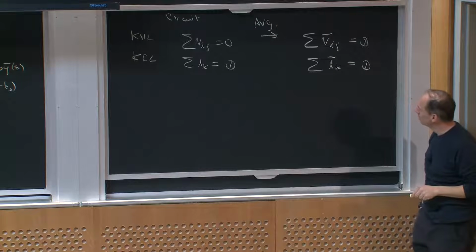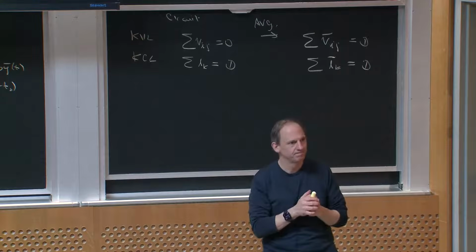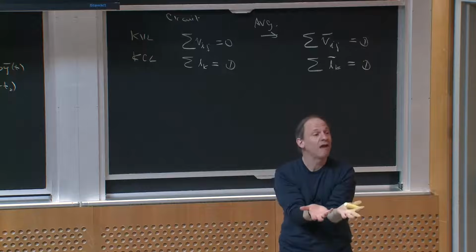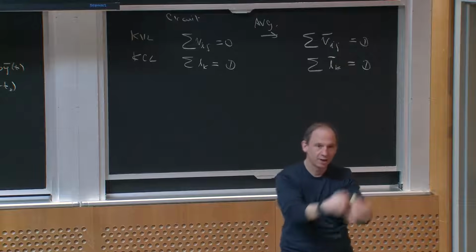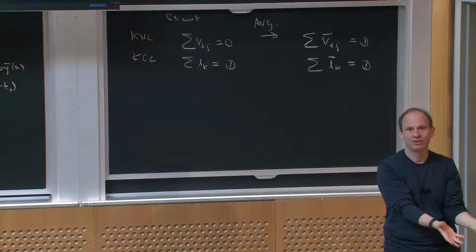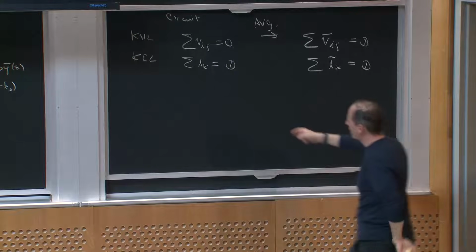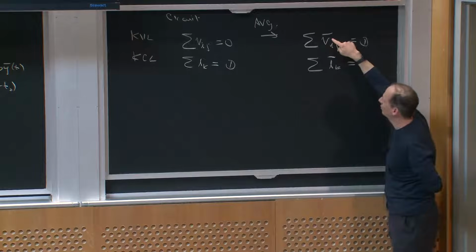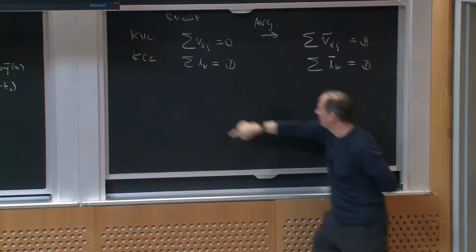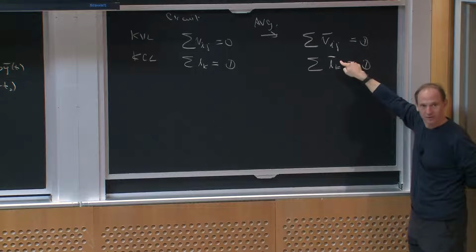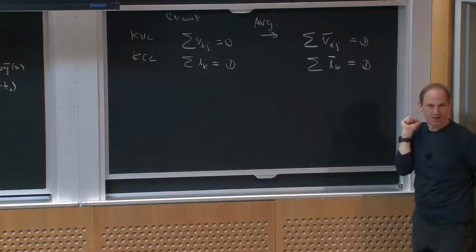Okay? So what I'm really saying here is if I have some circuit, like my boost converter up there, I could apply averaging to that circuit, or all the KVL and KCL equations, and I could get another circuit that's averaged that has the same connections in it. Why? Because for every KVL equation in this circuit, there's an identical KVL equation in this circuit, and it just has average voltages. And likewise, every KCL in this circuit generates a new KCL equation, just with average currents. So I can get a new circuit with the same topology for which averages pertain.